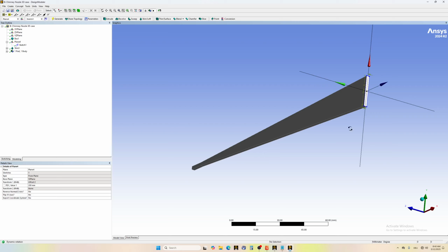But we will draw a region outside, which we will call pressure outlet, and that has a vacuum pressure of a few millibar or even less. So let's draw it, and for that one we will, so keep in mind this part is 20 centimeters from here, here is the inlet.